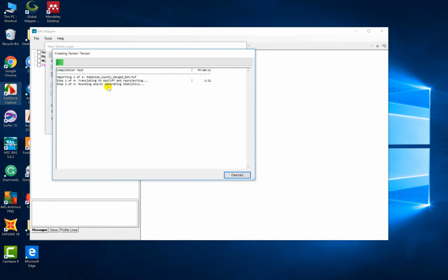Okay, I got it. So here we just define the flow at these 3 points, and we will assign that the water is flowing by gravity with its normal depth. So we will get the flow here. So we define 3 upstreams and 1 downstream. Okay, I got it. That's what we are going to do.